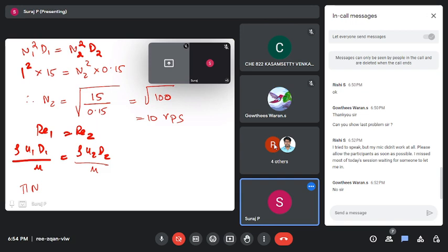We have considered this circular pipe, and from the textbook result we have the relation between shear stress and the pressure drop as tau equals delta P divided by 2L into R. We are substituting the pressure drop, 500 Pascal, that is delta P, and the length and the radius in this equation and calculating the shear stress.